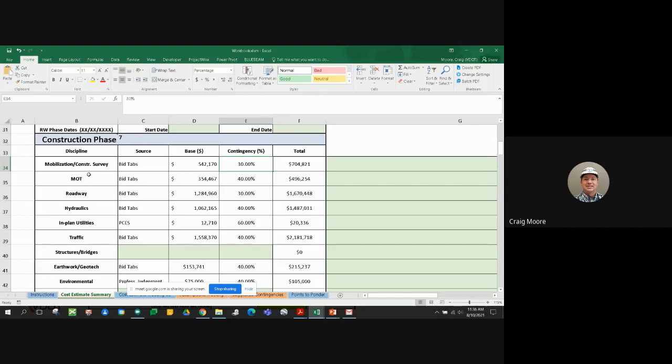One would maybe think, well, maybe we've eliminated some of the risk with the hydraulics aspect of it and our drainage. However, we haven't done channel adequacy calculations, and so we need to have a little bit of coverage in addition to that 30% for those other unknowns, and that's the reason our hydraulics here is set at 40%.